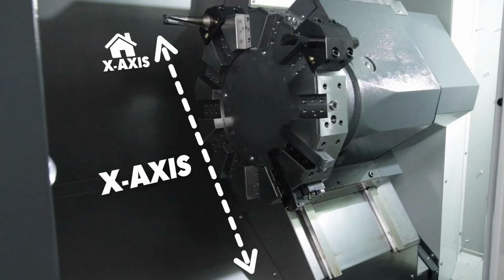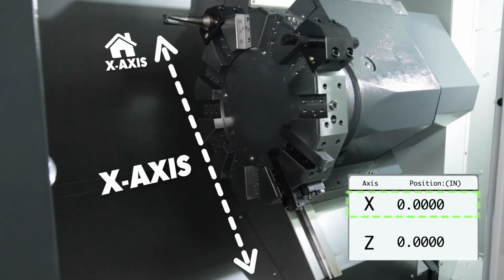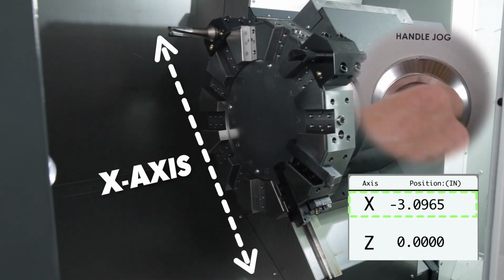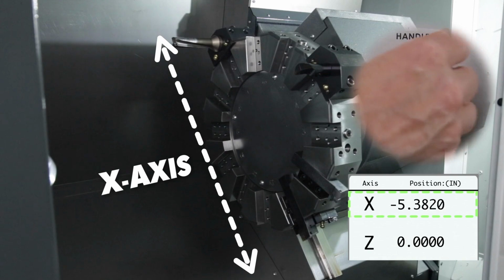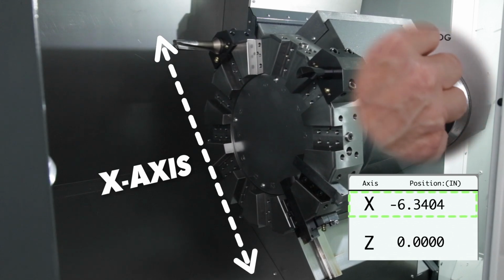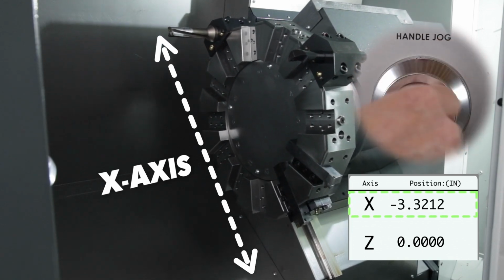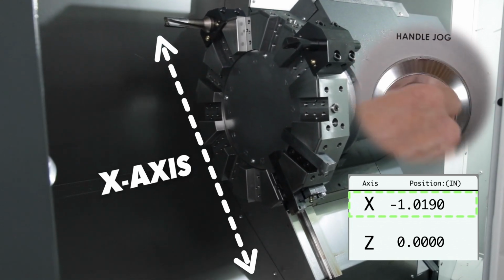Home position for the X-axis is all the way up, and it acts the same as we saw on the Z-axis. As we move the X-axis down towards the center line of the spindle, the position readout becomes more negative, so we're moving in the negative direction. Now, as we move back up, the readout becomes less negative. Now we're moving in the positive direction.